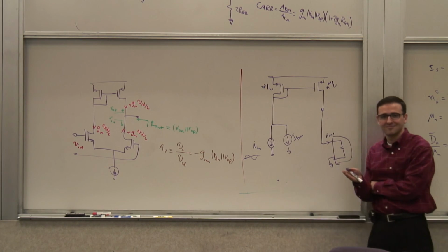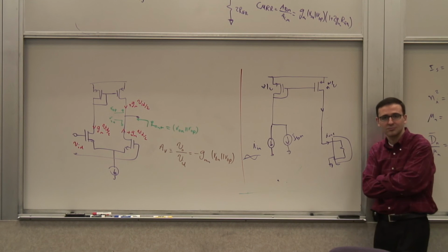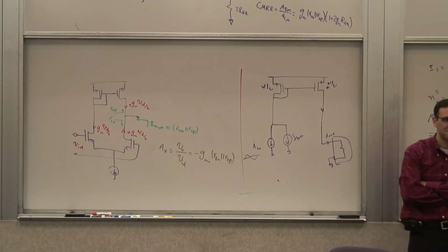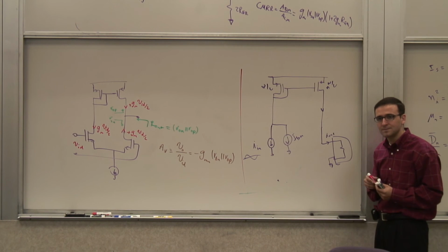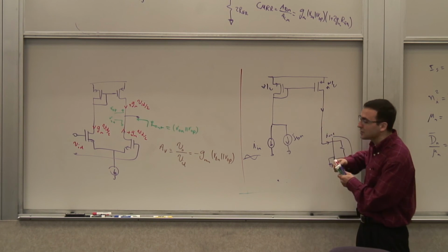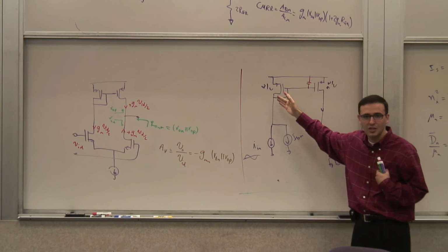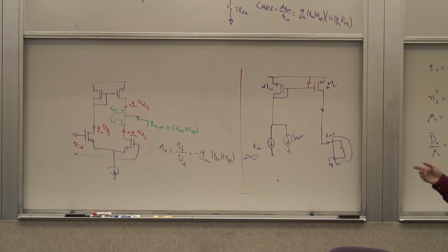So, can I make this n 10 to the 10? Well, of course, there will be some physical limitation. The transistor becomes so large. But other than that, I can make it quite large, at least in theory. So what would be the limiting parameter here? What would be the manifestation of the whole free lunch principle? Frequency. Well, okay, cutoff frequency. So let's think, capacitance larger and larger and larger. Yes, it will still be a current amplifier, but if you make it a million, it will probably work up to several hundred hertz.